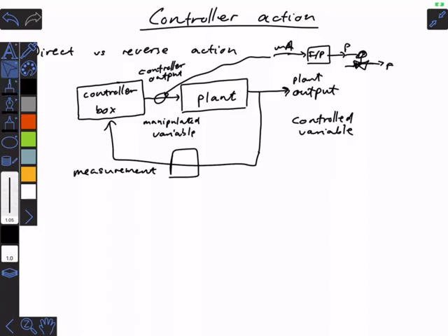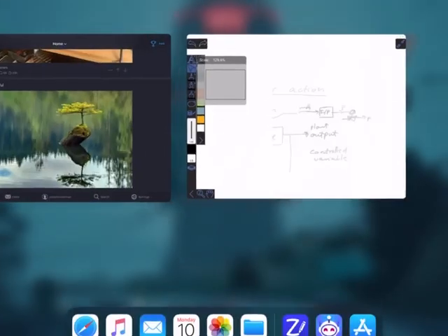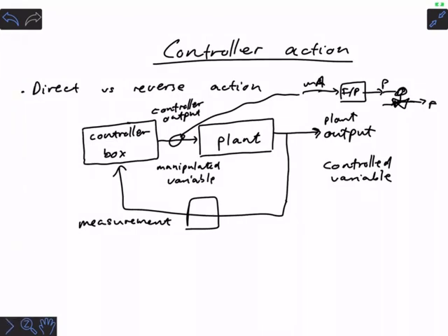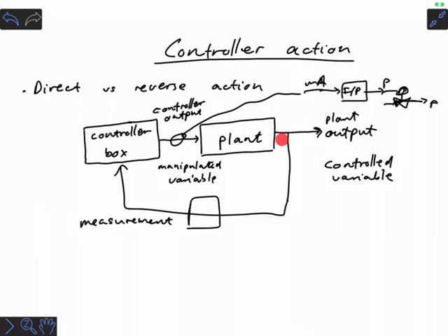So we wouldn't say that. Again, if I told you that I was trying to control a level in a plant, if I knew that my level measurement was kind of patchy, it was slow or it was noisy or whatever, I would still say that I'm trying to measure the level. I would just say that my measurement is delayed. And so there's a difference between the value that I measure and the variable that I am attempting to measure. Is that clear to everybody?